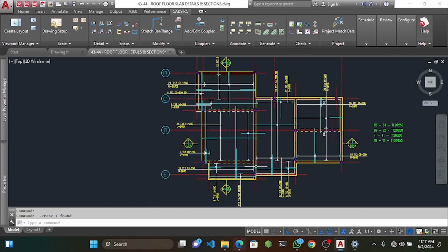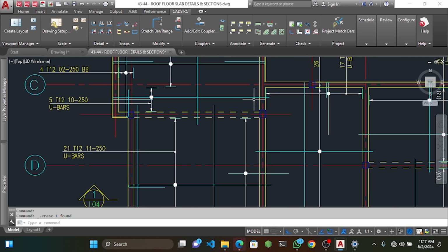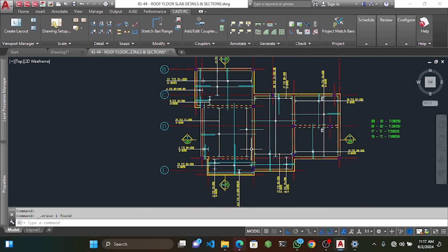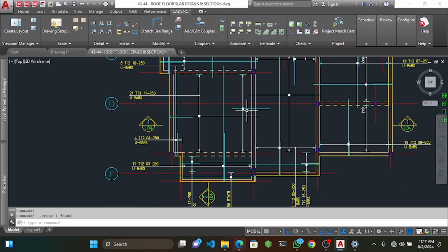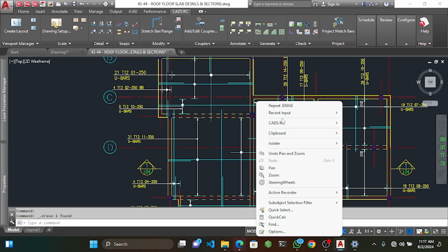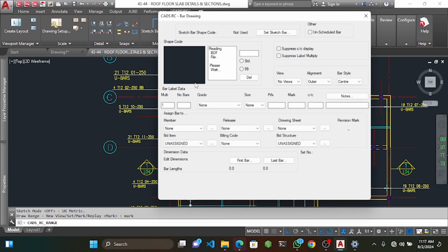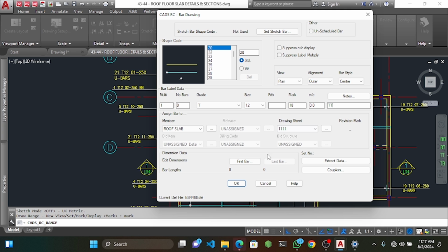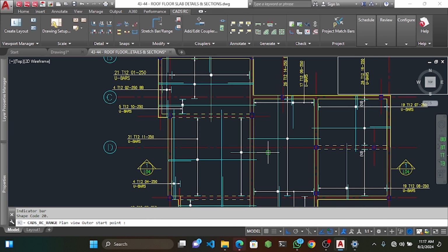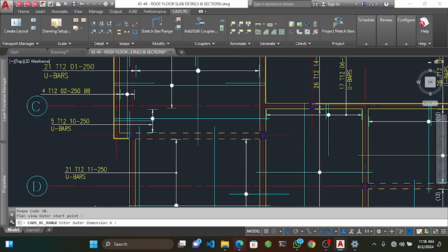I have this. So now I still need my support reinforcement here. I also need down here. So what I can just do for this part is to draw range, new mark, single indicator, then you come here, top, you can just snap to this point here. Then for this side, you already have one here, you snap to this place. You already know it's the same extent to this side, so you snap here.